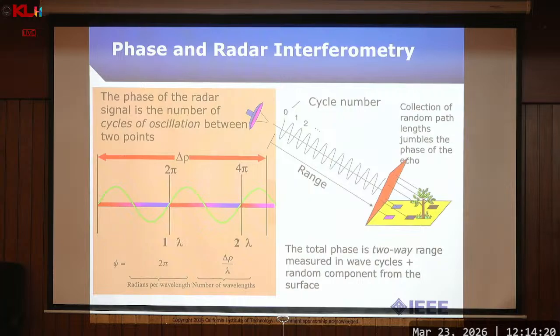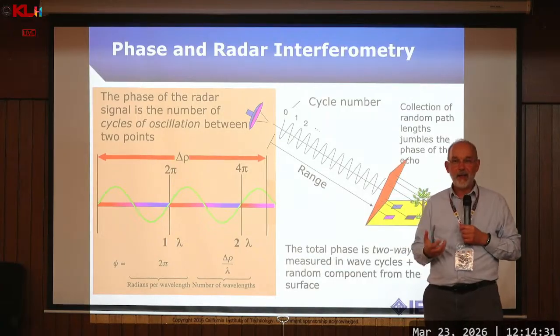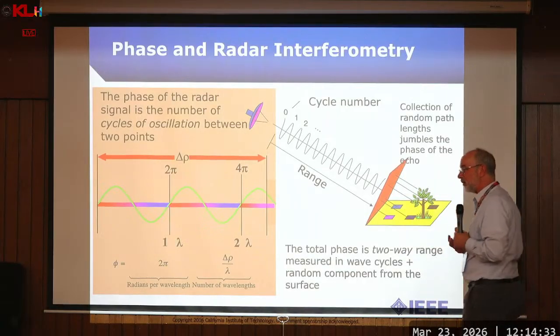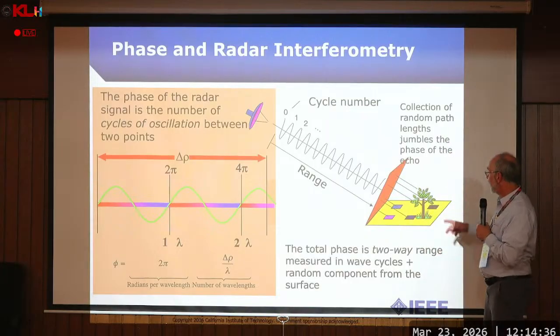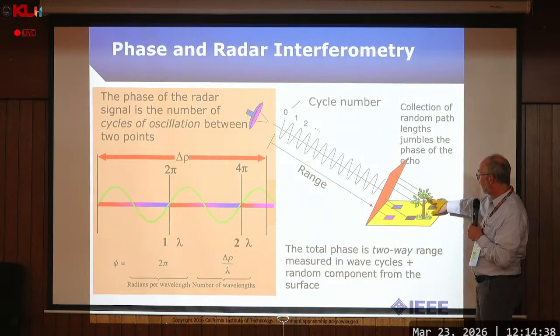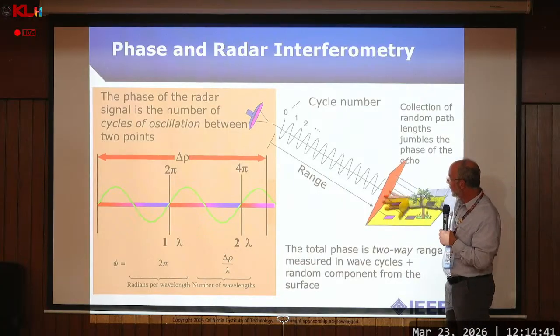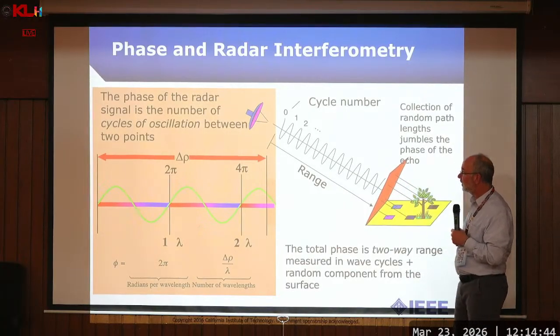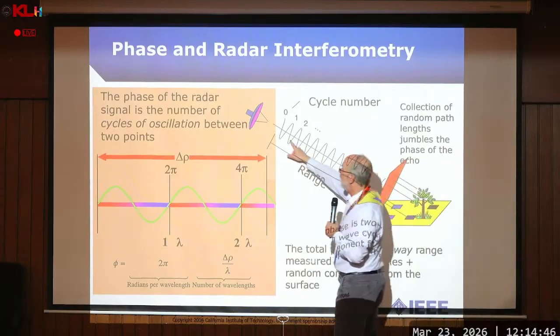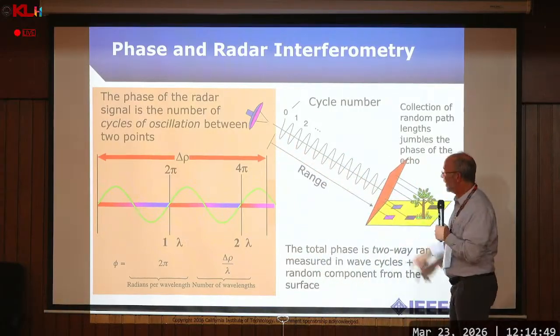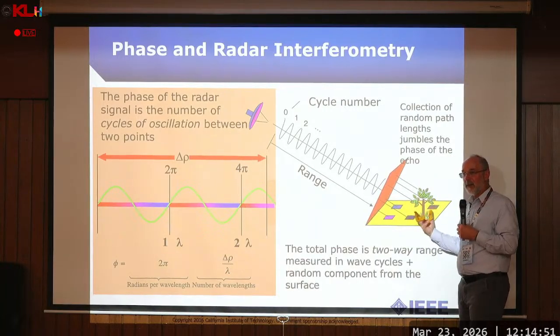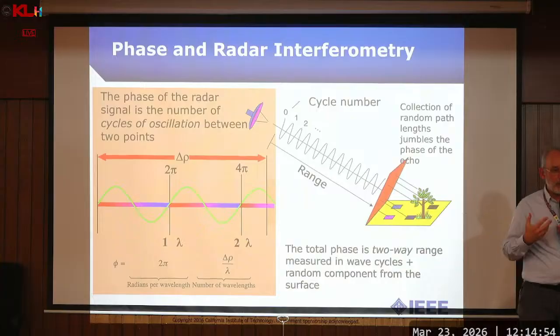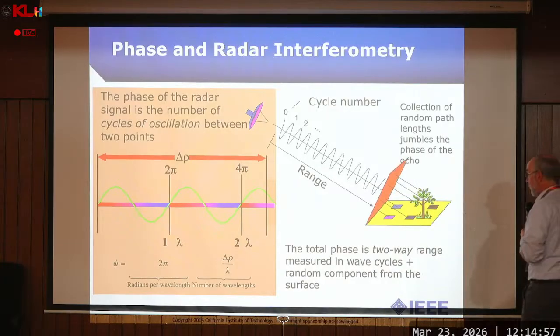Okay, so we've talked about backscatter per se, we've talked about polarimetry, now we're going to talk about how we can use the phase of the signal itself. I told you before that it's a coherent speckle generating system. So for these random scatterers on the ground, you will get a random phase of this pixel relative to the next pixel. The propagation distance here is deterministic. And so from a single radar image with a random phase, we can't really say much about the phase.